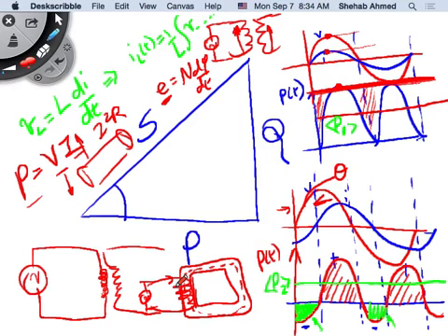If you go back to basic electromagnetic theory, if you have a turn with a time varying flux inside the area, you just have one piece of wire and a time varying magnetic field. What's going to happen across the terminals of that piece of wire? You will get a voltage across it. That voltage is equal to the time variation of that magnetic field. And if you have many of those turns and you put them in series like we did for the transformer, then you have a higher voltage due to all these turns linked by this flux that's flowing in the core.